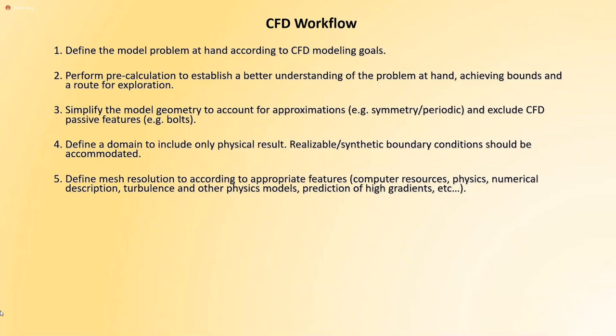Define a domain to include only physical results. Right, this is very important. You should look at it this way. I mean, and there are rules of thumb, we're going to get there. You wouldn't like the numerical boundaries to impact the location where the solution counts.